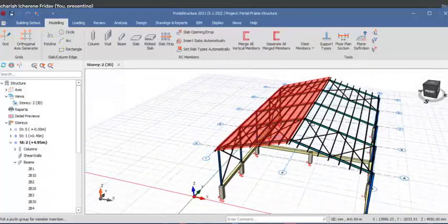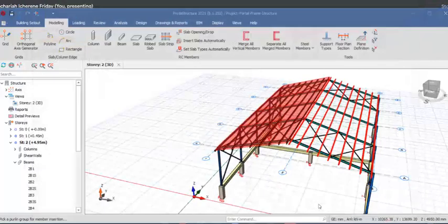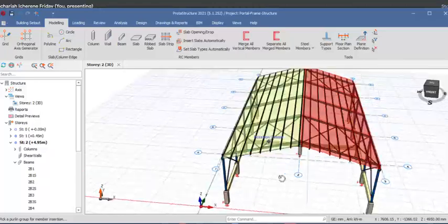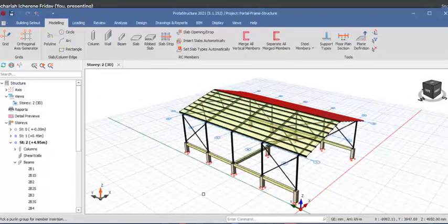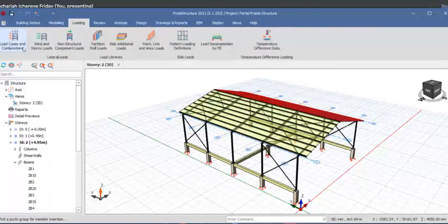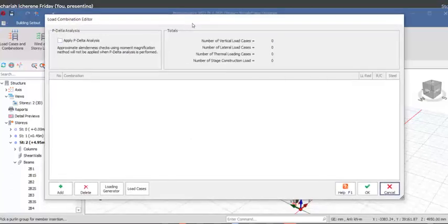So we can also place cladding on this other face by going to the steel members, cladding right there, pick the steel polylines, and then when the cladding dialog comes up, click on the OK option to apply cladding in that provision. After which, what you now have to do is activate the loading. So you come to loading right there, the load cases and combinations. You can see this whole place is just vacant and blank. That is why we are having that warning that came up.